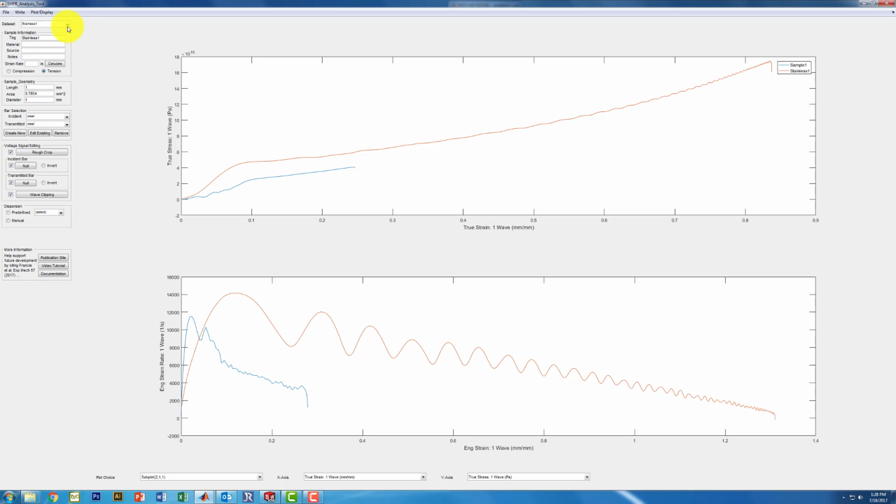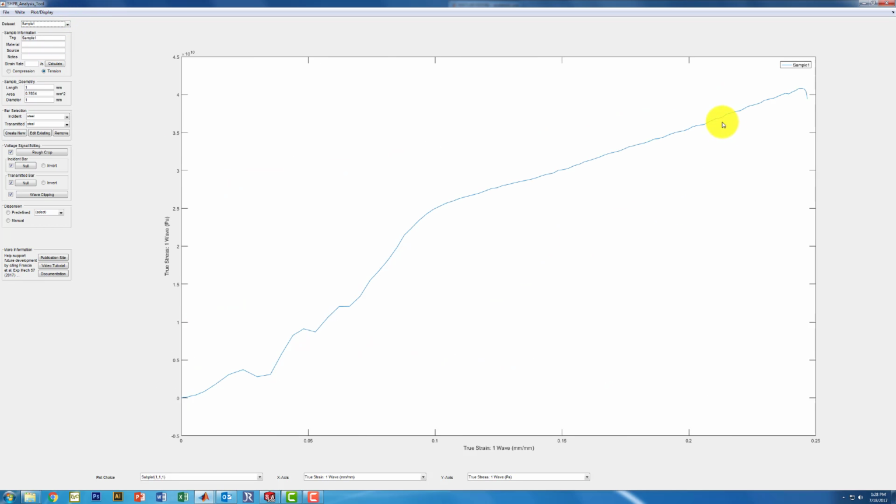Oh no, before we write, you also have the option. Say you had 20 data sets in here and you didn't want to look at them all at the same time. You'd completed all the analysis portion, but you wanted to just look at one at a time or something. What you can do is right click, or pull up a data set. So say I want to look strictly at sample 1 and I don't want to look at anything else. You can right click on it and you can isolate the plot, and now if I go back and replot, it will just be sample 1. And you can unisolate any plot. And also, if you had 20 sets and you only want to look at half of them, you can disable the plots that you want or enable them so you can view things inside here.